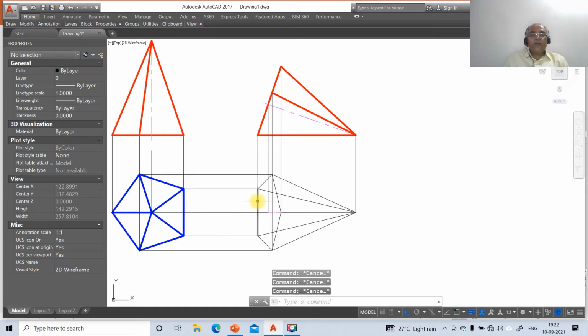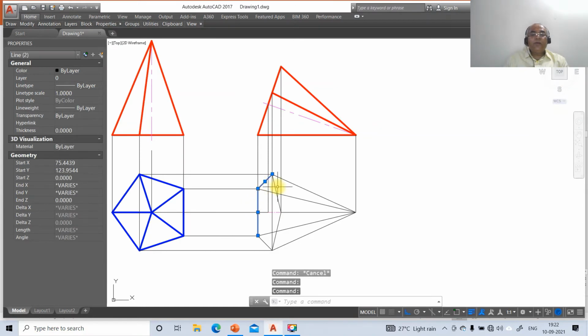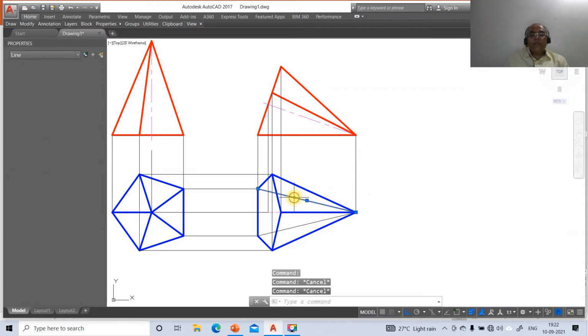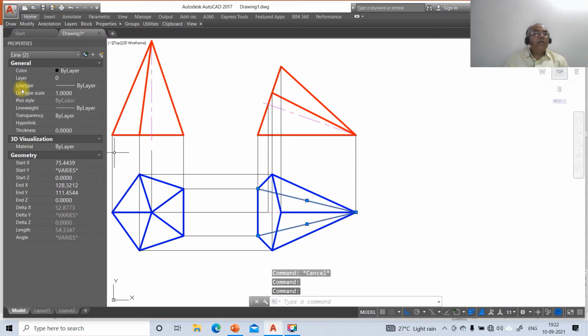Then you just click on this, and then all the exterior edges of the boundaries of the solids are visible and the surface near to the observer is visible. So this line is also visible. So you make this as top view. Once you do that, you just click on this and you click on this and go to layer, make that layer as top view hidden and take this dimension as 15.